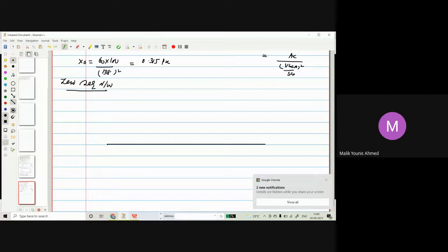So let us put it here like this. Okay. So that reactance is solidly grounded, and solidly grounded means reactance is equal to 0, so we don't have to mention it. We'll consider only this reactance for the generator, and the reactance we have seen in zero sequence is 0.15. You can check it also.